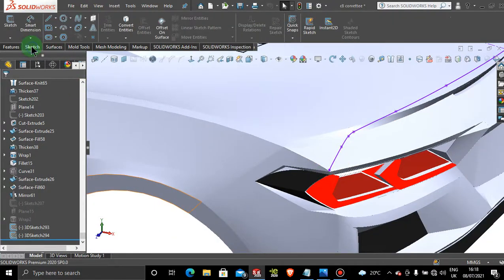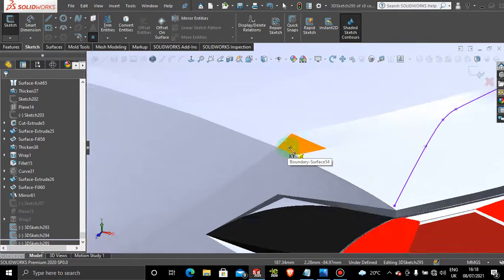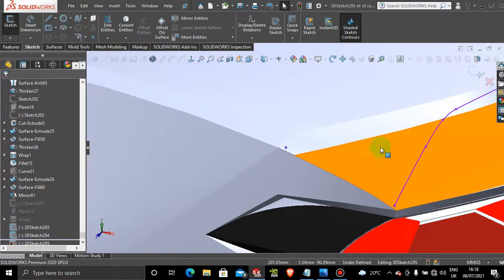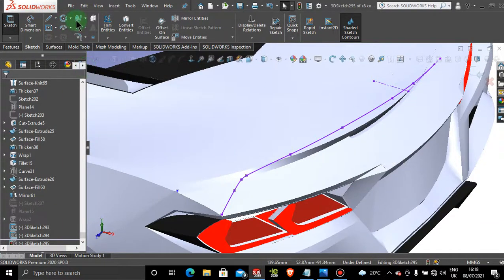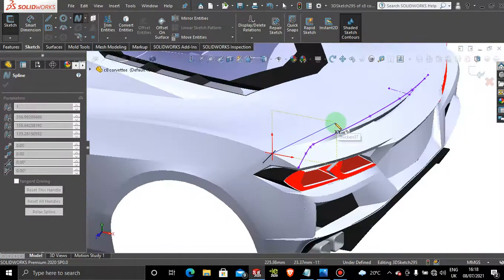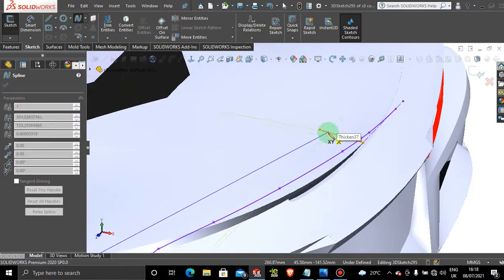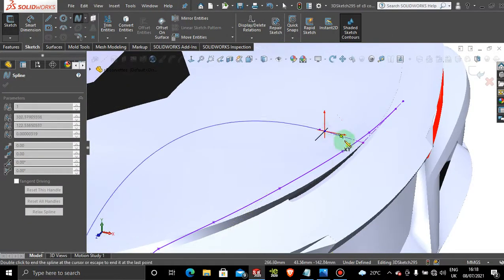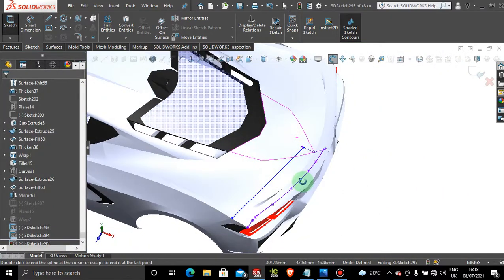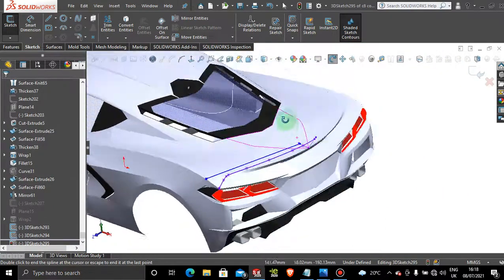And let's jump into another 3D sketch, and we want the 3D point, and we want to drop that point somewhere here. And then let's grab that spline and drop that spline on this point to this line here. So again, realize I didn't snap it on the end because we can adjust it afterwards.